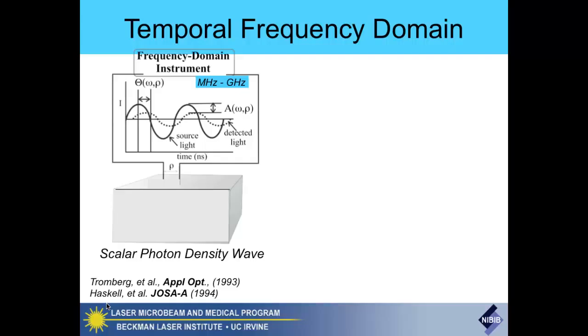But if I give it too much current, then the system collapses, and I get no more lasing. Things are clipping. So I can't have RF with amplitudes that are too great, or else I'll get nonlinear harmonics generated in my laser, and everything will be really weird. So I have to make sure that the RF amplitude is just the right amplitude so that I'm getting very beautiful sinusoidal modulation. And so you can tune your lasers with that.